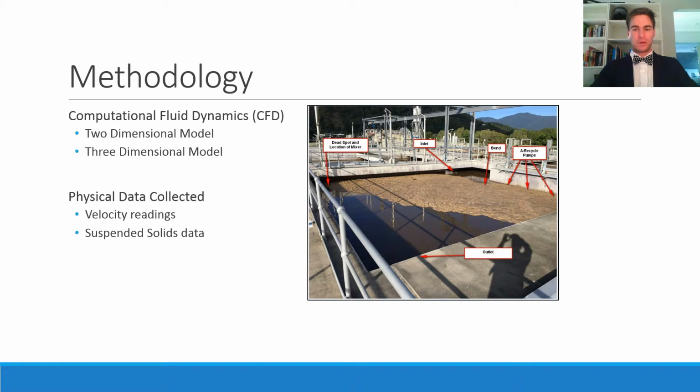The CFD model was created in Ansys using their design modeler. Once the geometry of the model was constructed, it was then imported into the meshing platform of Ansys. The initial model was constructed with the default meshing options, and then the mesh was refined. Once the model had its mesh, it was then imported into Fluent, where the boundary conditions were defined, and then the simulation was commenced, with the results being recorded.